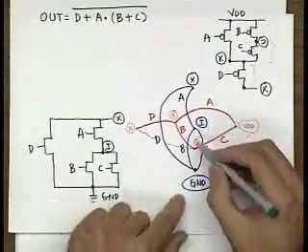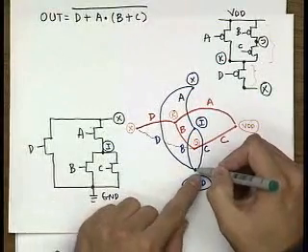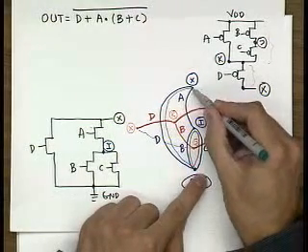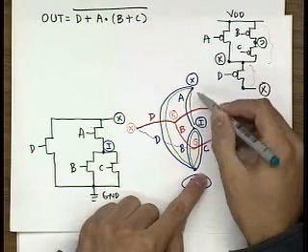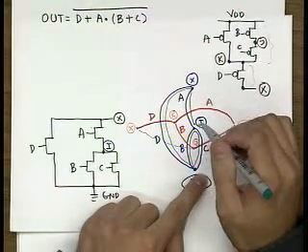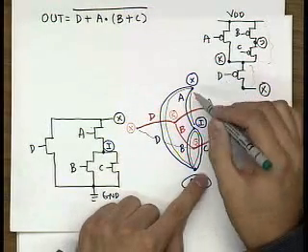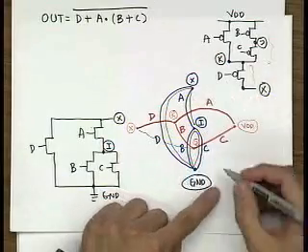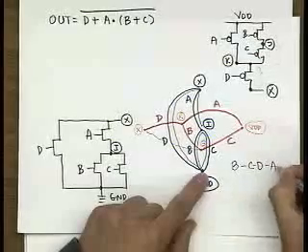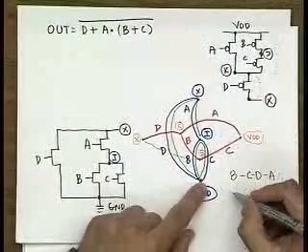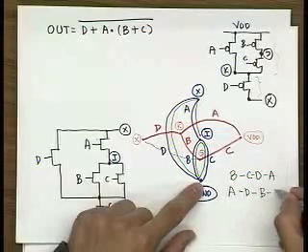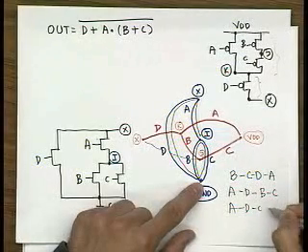An example of an Euler path is, for example, let's start from ground. So you have B, you have C, you have D, and then you have A. You go around through this graph and visit each of the edges exactly one time. This is called an Euler path. And again, there are a number of Euler paths you can identify here. You can, for example, go B, C, D, A, or you can go in the reverse direction, A, D, C, B, and so on.